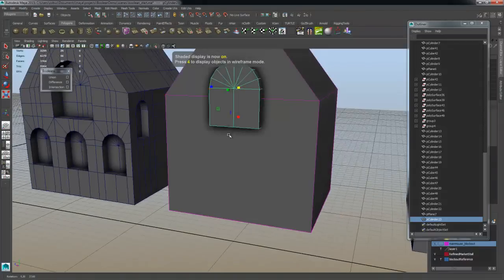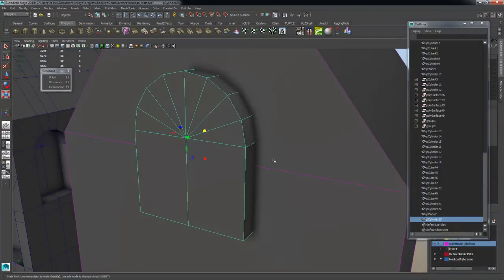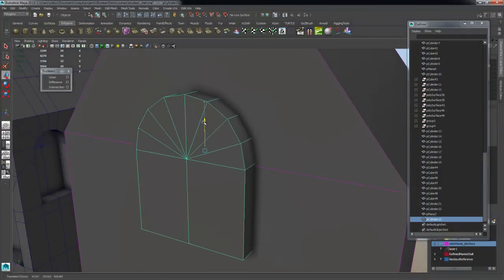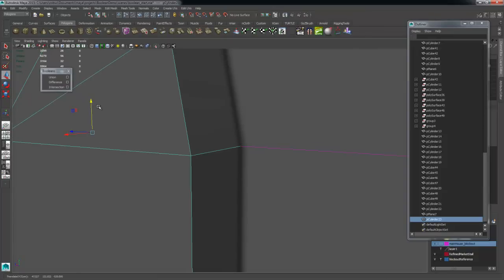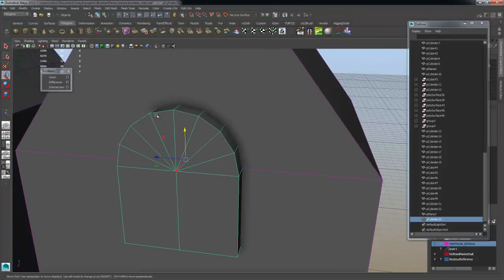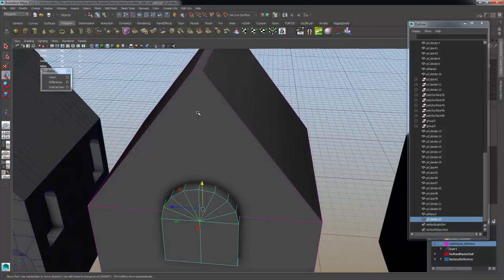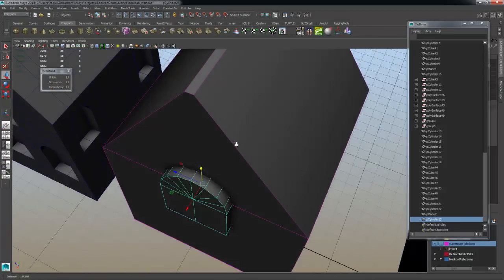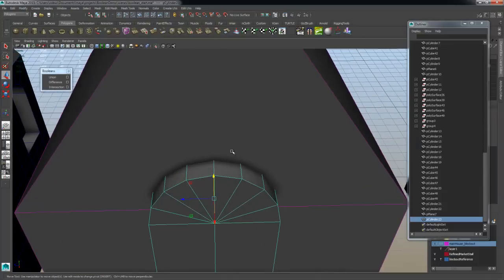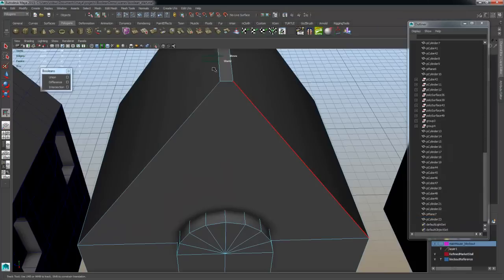Great stuff. Now that I have that, I'm going to go ahead and align these edges to the existing edges on my model. This keeps it nice and clean, so once the Boolean operation is done, I can then easily connect these edges together, and I know where they're supposed to be connected to. For the same thing, I could also say that maybe we should have a center axis running down the center of this little house. That's going to allow me to connect to this edge. And maybe that's a good thing, let's tackle that first.